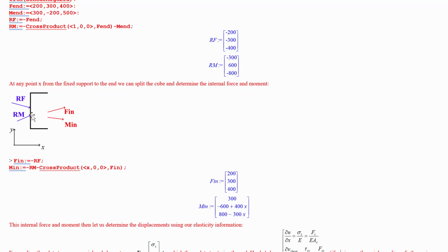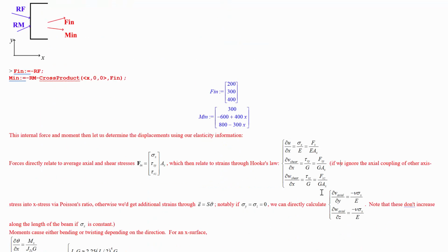vertically if we've got the x and the y, rather than rotating in the x direction, rather than the sliding along the x direction, then it's okay for you to say that this shear strain, which is really the sum of those two things, del v by del x plus del u by del y, is entirely manifested with del v by del x. So the shear strain will be just this del v by del x, and that means we can say that del v shear by del x is equal to tau xy over G.